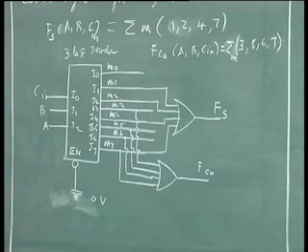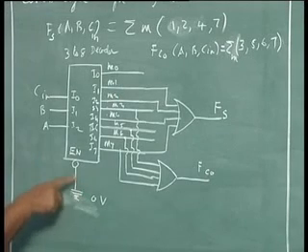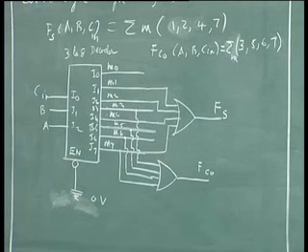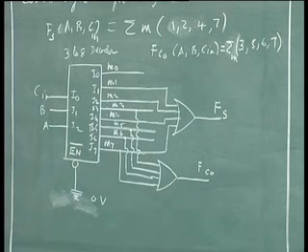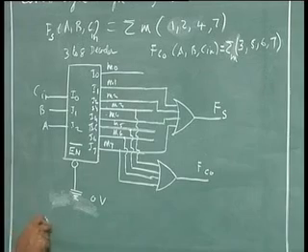Usually when you say enable, if you want to be very clear, since you don't have the circuit diagram, every time you are talking about a decoder you cannot draw a circuit and show enable as a bubble. So what you say is simply enable bar. So people understand. When you say the circuit has an enable bar, it means I should make it 0 for it to be active, for normal operation. So enable 0 is normal operation.